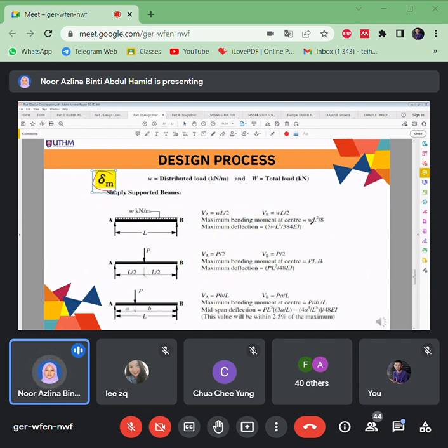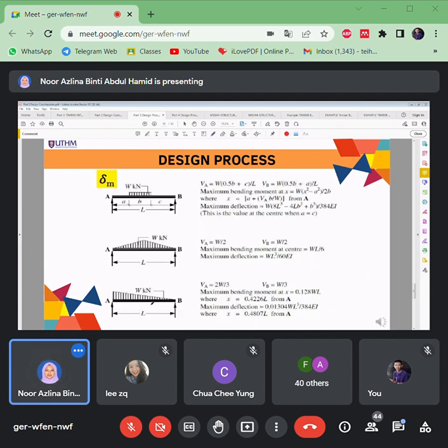Okay, what's the bending if the beam is loaded uniformly? What's the deflection here? This is the deflection according to the bending. So just use this formula according to the load that is applied on it. Is it uniform or point loads? If point loads, is it exactly at the center or at some proportion? Or rectangular or triangular uniform loads.